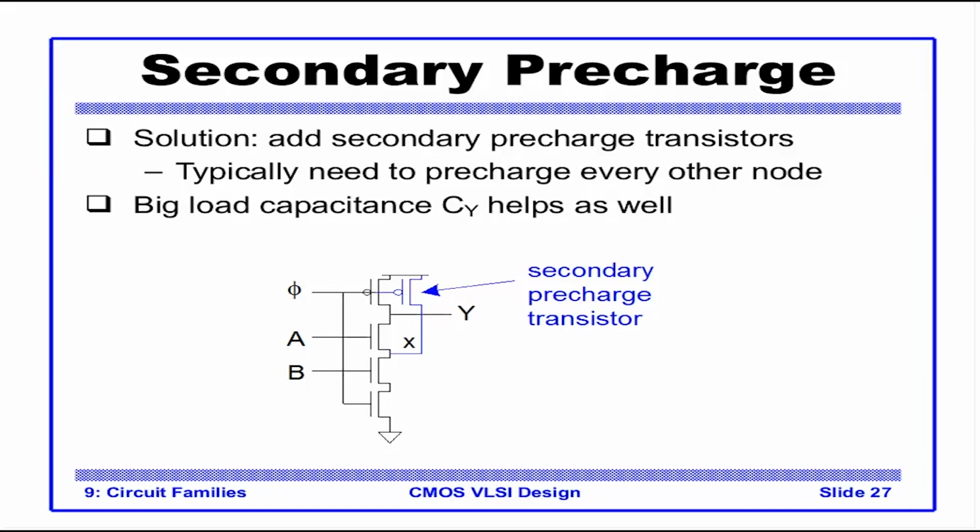Even more specifically when you consider small gates, like 2 input NAND, 2 input NOR, majority of the gates are 2 or 3 inputs. Now in case of 2 or 3 inputs, the area advantage offered by a dynamic logic or a domino gate is not much. Right? Such a circuit might be even bigger than the corresponding static CMOS.